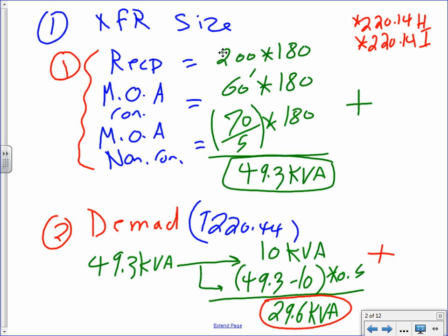Okay. Grab your DeWalt, will you? And go to 7-7. Very important page in DeWalt, 7-7. Now, Jeff, when we size transformers, we size based on industry standards, not based on what we like. I have 29.6 kVA. Either I have to call Square D and ask them for a custom design at 29.6 kVA for me, or I'm going to be using the standard industry sizes. Why do we care about industry standards? Because that's what the electrical contractors will be buying to install, guys. That's the actual equipment you're going to be installing.